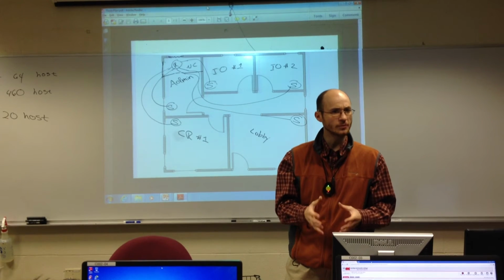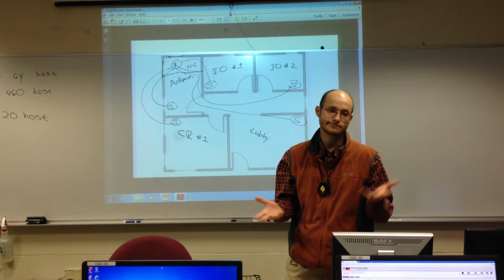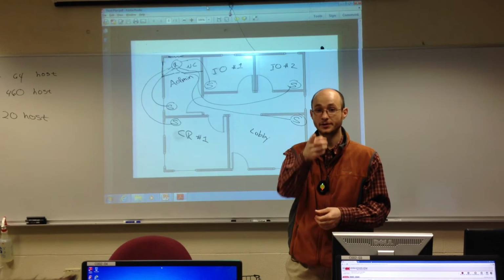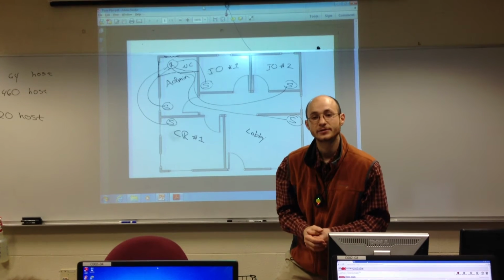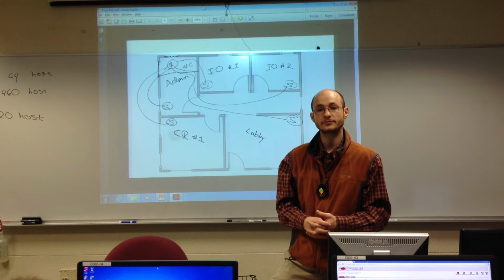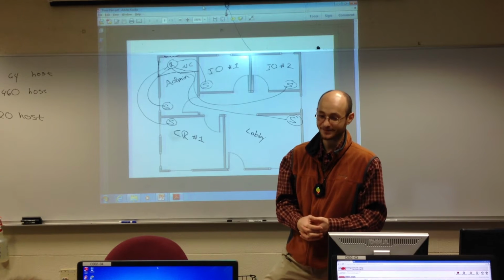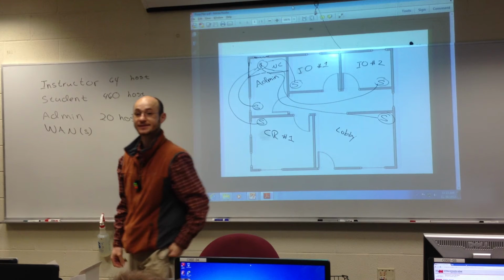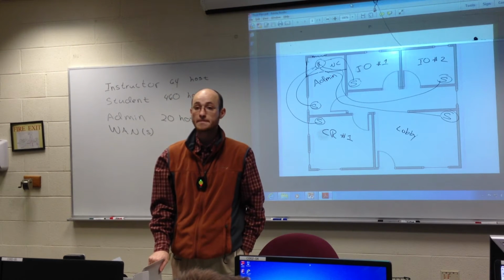Would it be a good idea to terminate all of those bundles? Doesn't matter, really. It all depends on how many ports you have available on your switches. Now, when I worked construction, I don't know if this is common practice, but the dude that was with us, the electrician, was running new cables, and he had a wad of network cables this big, and he used soap detergent. Yes, I'm glad you brought that up. Pull it through. I'd never seen or heard of that done. Yeah, I do it all the time, especially if you're using conduit. They said it's the only good thing to use.